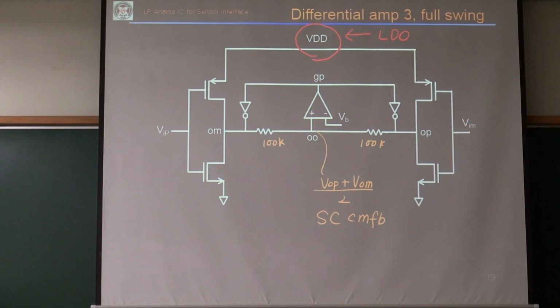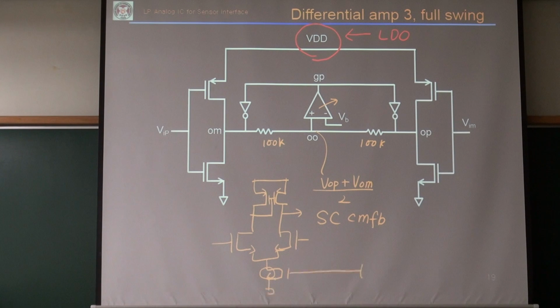For this simulation, we need the ideal op-amp for maybe voltage gain of 30 or 100 or something like that. But in your homework, you have to replace this one by some transistor, active load one. So you may use some current source, or maybe you can use something like that. You can use some small current.